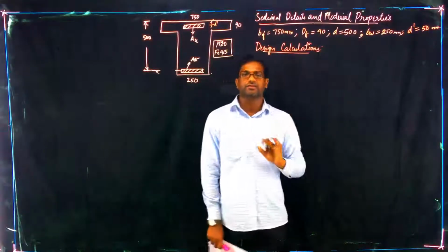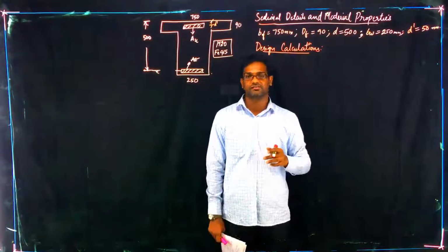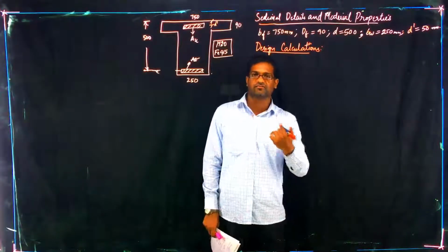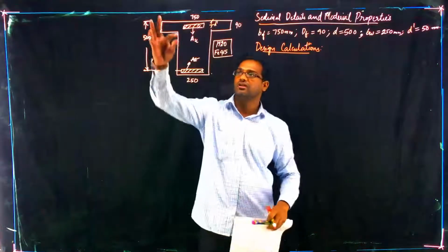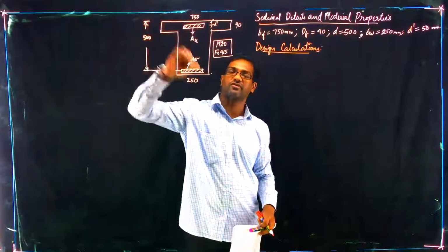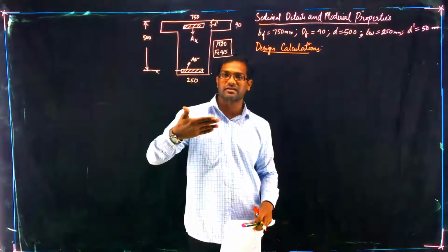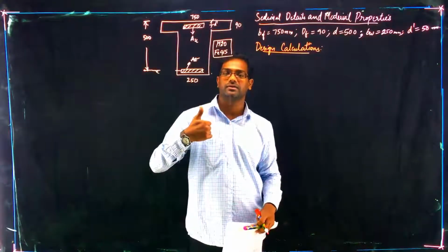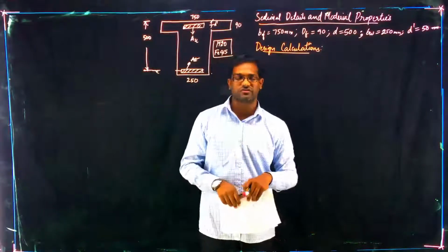The design calculations of the T-beam and this doubly reinforced T-beam are the same. We need to assume the neutral axis length, and then we have to calculate MU1, if you remember the steps. The neutral axis is assumed within the flange, and we calculate MU1. If MU1 is less than the moment applied, then we say the neutral axis has shifted. The same procedure will be followed here.